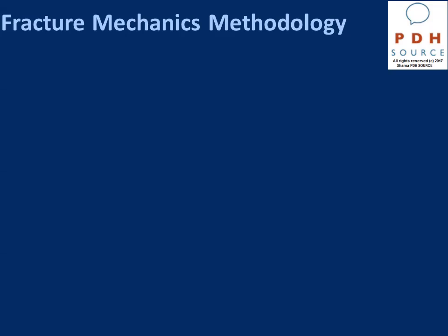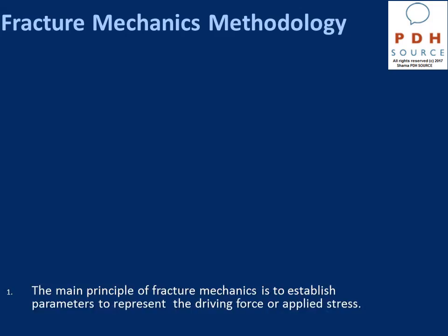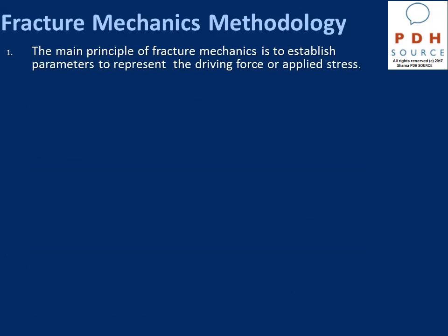So there is a fracture mechanics methodology that can be used for this purpose. Now, the main objective of this methodology is to establish parameters to represent the driving force or the applied stress, and establish parameters to represent the capacity of the crack.